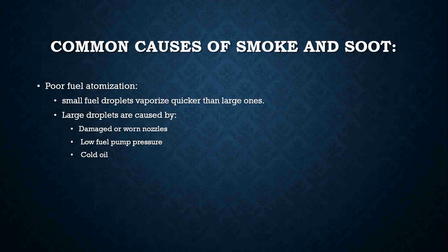You can have low fuel pump pressure, which is again why it's always important to take fuel pressures to see what you're actually pumping at. Or you have cold oil. Remember cold oil, viscosity, all that stuff takes effect as to why you're having smoke. Sometimes as the oil heats up, the smoke goes away.